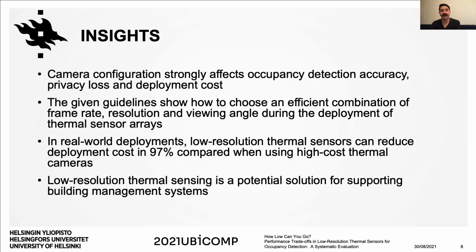In this article, we provide a novel insight about the use of thermal sensors for occupancy detection. The effect of having different camera configurations showed, for example, that even low resolutions is more than sufficient to estimate accurately occupation, as long as the sensor is well positioned, aligned, and has a high frame rate.